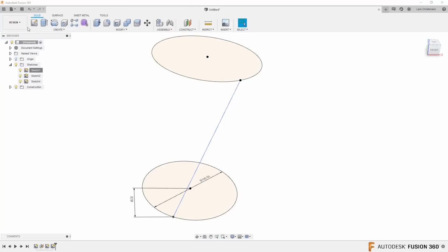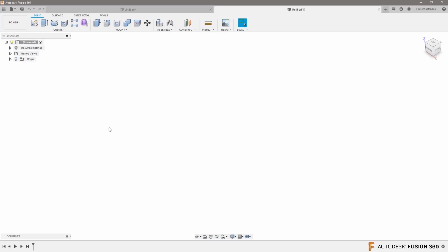Yes, let's jump into that and take a look at that. Now, let's just move on from our hyperboloid or however you pronounce that. If we talk about unflattening anything, then we're normally looking at sheet metal. So let's go into the sheet metal workspace up here. There's a little bit of a trick if you're trying to make a ring using sheet metal, in the sense that it can't be fully enclosed when you're doing all the fold and unfold.